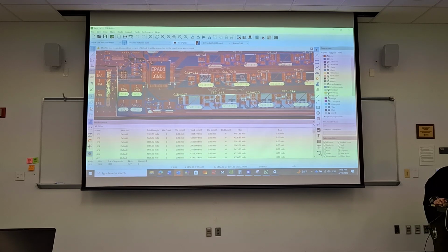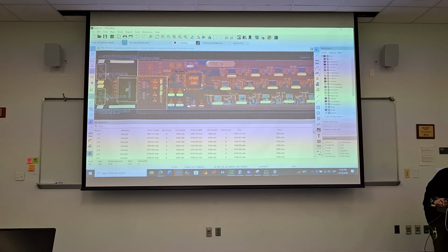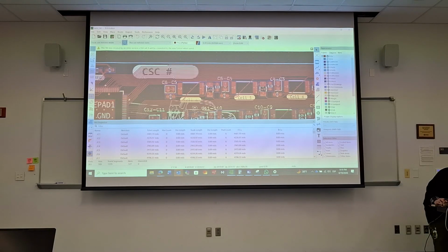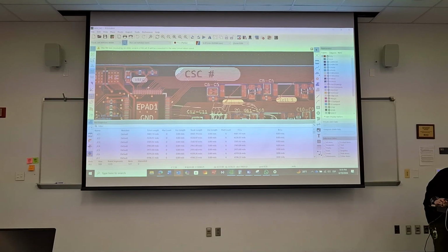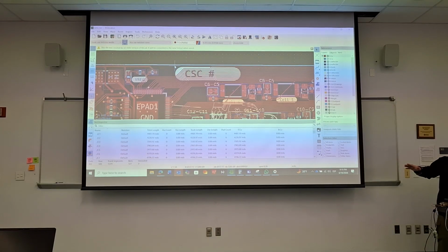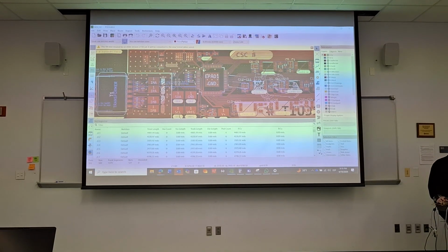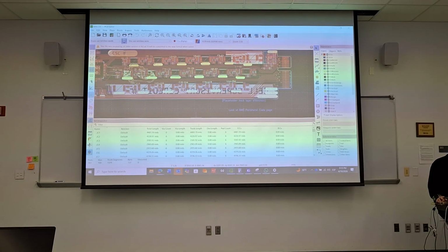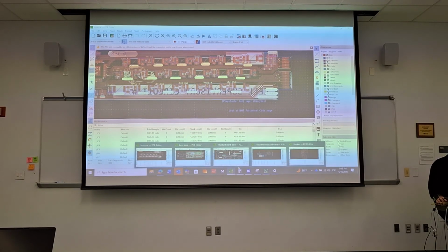This is another one where, I mean, it would also help to have the copper in the top layer so that you also have some shielding immediately next to the traces, if possible. This one's okay. Okay enough.